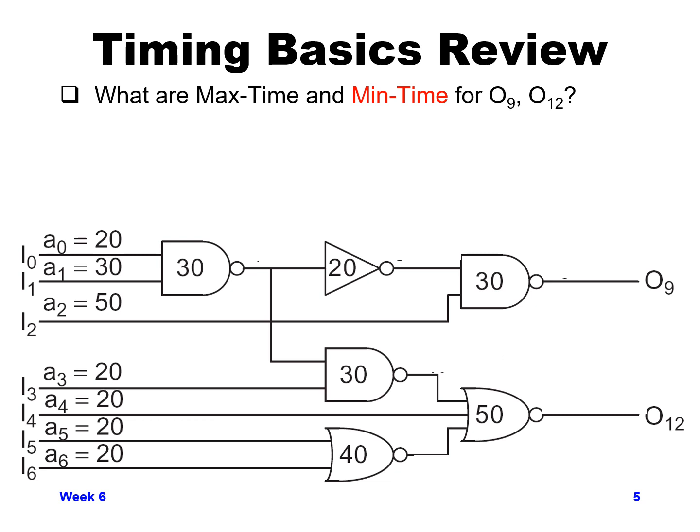I'll start going through the actual determining max delay first. We'll start from the upper left and work our way to the right. So the NAND gate in the upper left has two inputs, I0 and I1. They're coming in at times A0 and A1 of 20 picoseconds and 30 picoseconds. For max delay, we want the longest of those two. So 30 picoseconds is the latest. We add the 30 picoseconds of the NAND gate itself, and so the max delay coming out of that will be timing A7 of 30 plus 30 is 60 picoseconds.